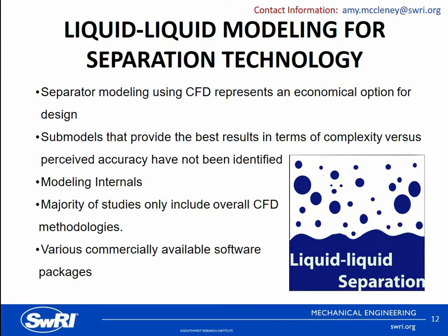Another way researchers have tried to minimize computational resources for separator modeling is by taking advantage of symmetry in the geometry to simulate only a portion of the domain, treating the flow basically like a plug flow. But researchers have found little success with this approach. Full 3D simulation significantly increases your simulation times, though, compared to cases taking advantage of perceived symmetry. Additionally, some authors do not even resolve the entire internal geometry of the separator, choosing instead to utilize porous medium models to represent certain internals, such as perforated plate baffles, in order to reduce mesh requirements.